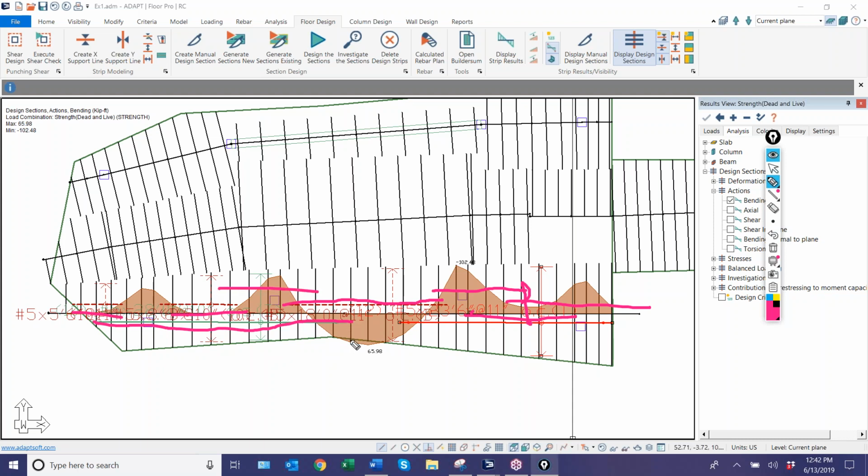So the rebar layout becomes a little bit different when you model it this way, but still you get a safe design in terms of strength if you do this. The problem comes where you model this only with 2 points in terms of service. If there is a service related requirement by code that is dependent on the span length, for example, 2-way PT slabs, the prescriptive rebar at the top or at the support is based on the tributary in either orthogonal direction.